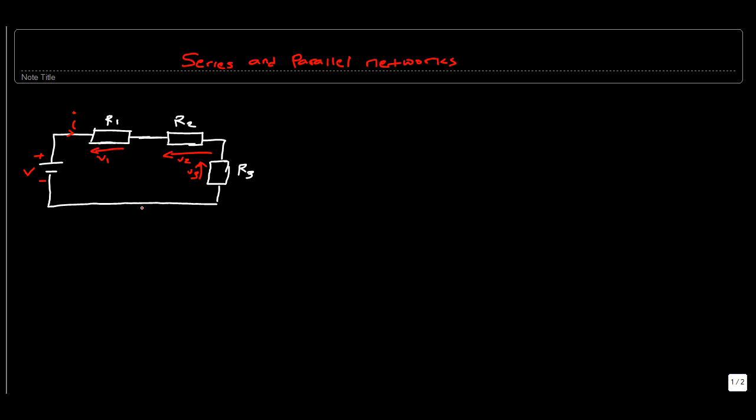Now we do have a closed circuit with three resistors, R1, R2 and R3, and a battery of V voltage causing a current I to flow in the circuit. We can obtain the potential difference across the three resistors by connecting a multimeter or a voltmeter to each of the resistors, and we can take values V1, V2 and V3.